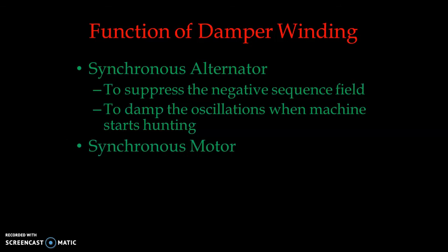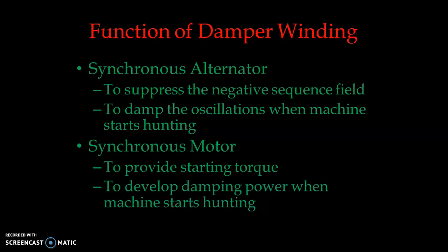Same way in synchronous motor, the function of damper winding is to provide starting torque. In case of synchronous motor, we know that it is not a self-start motor. Either we can start as an induction motor or we provide damper winding. So one of the functions in case of synchronous motor is to provide a starting torque. And the second function is to develop damping power when machine starts hunting.